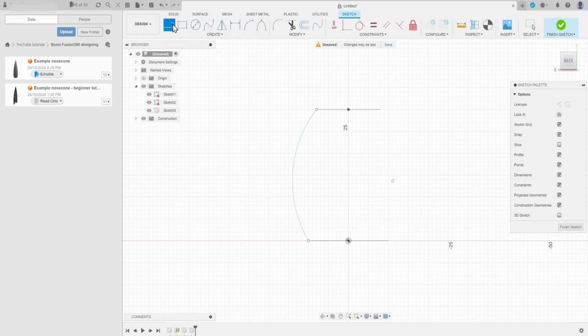Now, I'm going to press Line. In here, we can choose the line type. I'll choose Center Line. Because this is a center line, I'll make it right in the center just like that. Now I'll just press Tick. And then, instead of having to copy that one exactly on the side somehow, we just choose Mirror. This is exactly what it says, it mirrors it. Now, because we've chosen center line on the line, the mirror line is already selected. With objects, we just select our curve. And now I press OK.